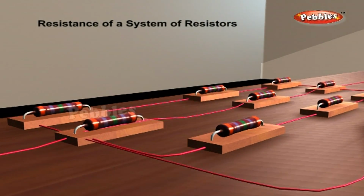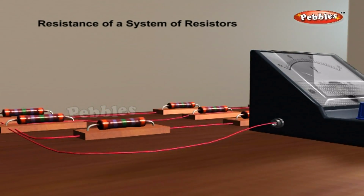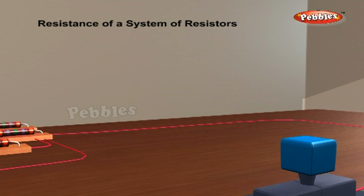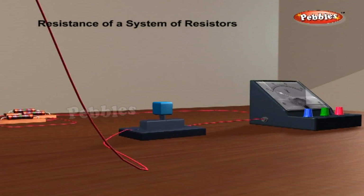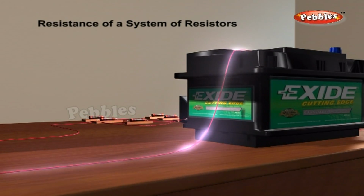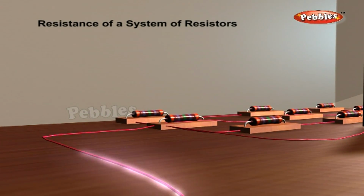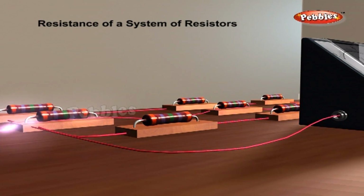Also connect a voltmeter in parallel with a combination of resistors. Plug the key and note the ammeter reading. Let the current be I. Also take the voltmeter reading. It gives the potential difference V across the combination.